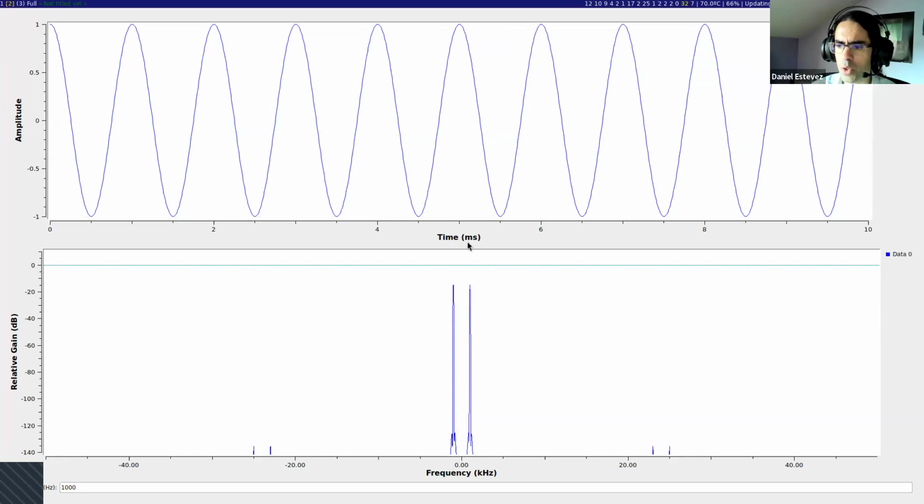Okay, the next thing I'm going to show is how to move things in frequency, because you can imagine that is an important operation. We are always thinking about time and frequency when we do signal analysis, and we want to select things in time. There might be a time interval which is of interest to us because that is when an event happens. And selecting things in time or moving things in time is very easy. We just have the stream of IQ samples in time and we select the time interval we are interested in. It's basically selecting some samples in the file or selecting some bytes in the file. It's just as simple as that.